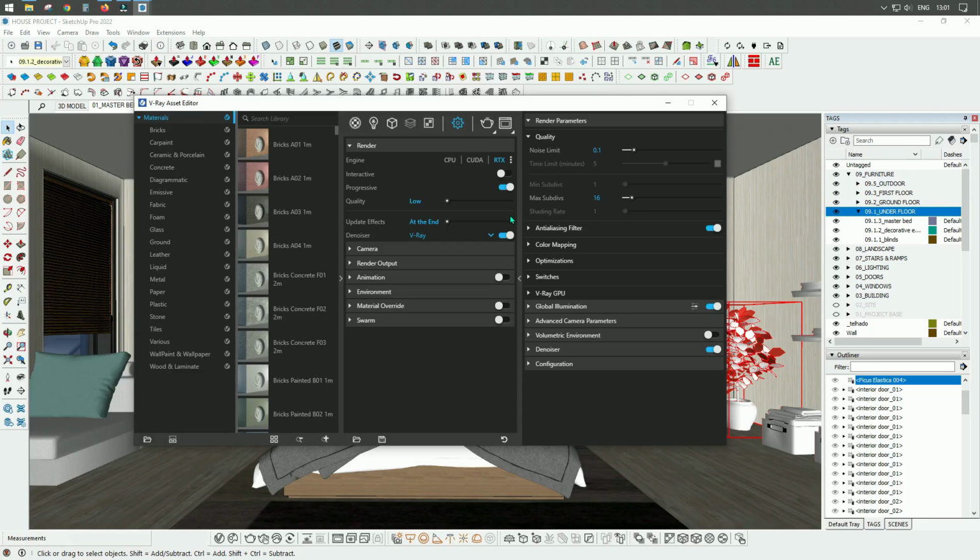for our scene. And you can render of course with the engine. This is CPU rendering, and actually here the scene will be rendered by using your CPU. V-Ray will use your CPU. This is some kind of a mixed rendering by using CUDA GPU and CUDA, something in between.